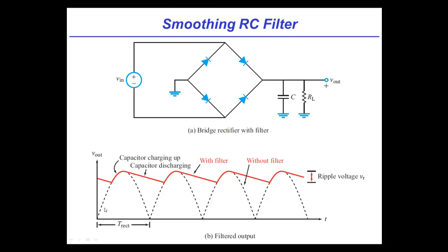Okay, so now the capacitor doesn't like changing as fast as this, for the appropriate size capacitor. We'd have to pick the right one. So that'll probably be a pretty big capacitor. Exactly. And remember, capacitors don't like these very fast changes in voltage. That's one way to think about this. The other way to look at it is this is just an RC circuit, and the RC has a certain discharge time. So let's look at it.